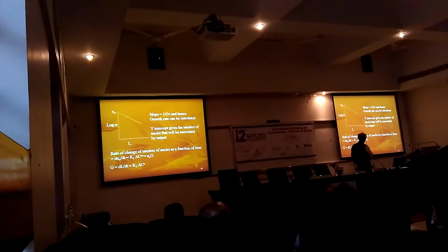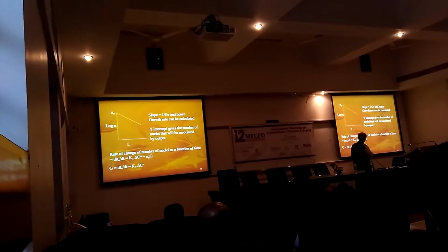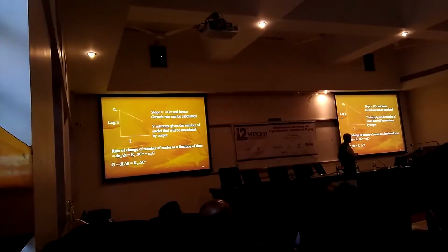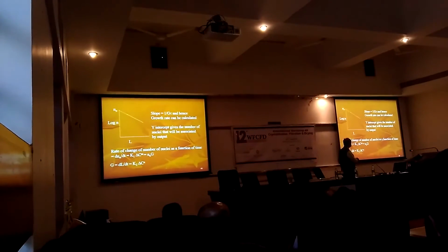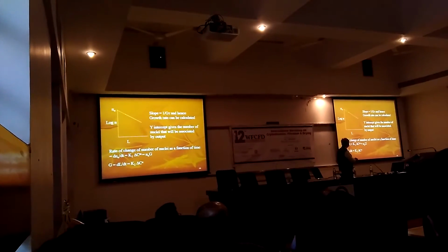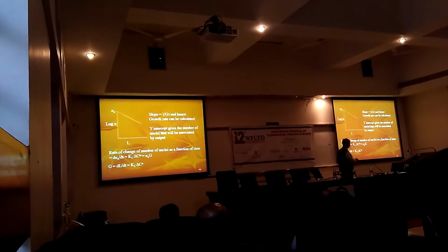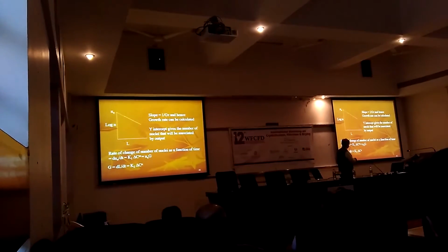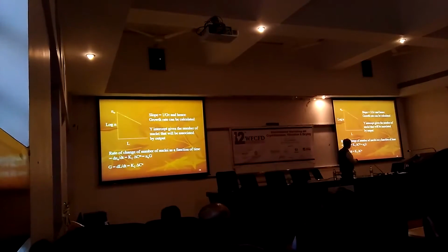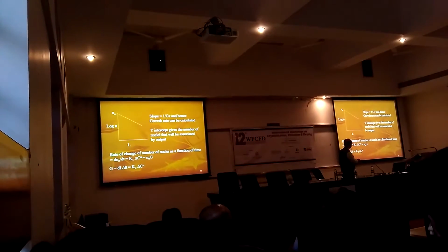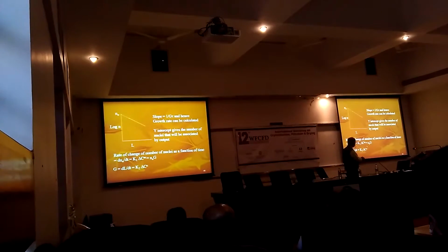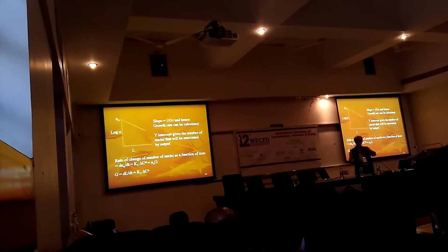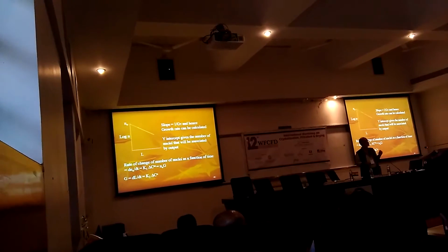So basically, the rate at which the number of nuclei are precipitating out or nucleating out is proportional to some proportionality constant and the degree of supersaturation which is responsible for it, and then supersaturation is also deciding the growth. So growth is expressed in terms of change in the length as a function of time, again with a second proportionality constant. The dependence on supersaturation for both these phenomena, nucleation and growth, need not have the same exponent.